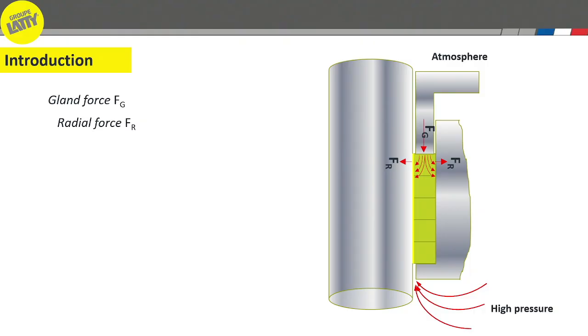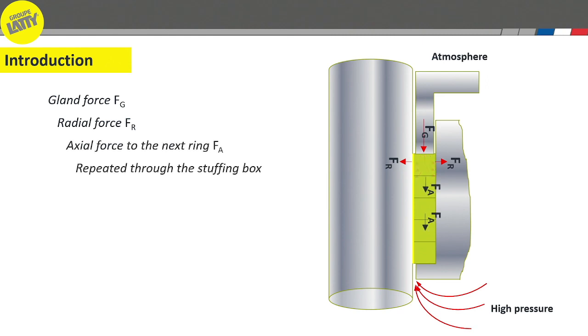The packing is seated due to the gland force applied by the gland follower on the ring stacking, which is converted to radial force and axial force, transmitted and repeated through the stuffing box.